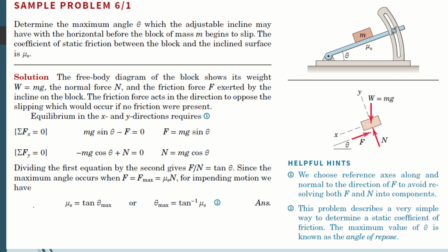So what is the maximum angle? Now this is again what you will get: the angle of friction, which we have studied in the second last article. How are you going to find this? As you know, a mass under the gravitational force field has weight mg. Since this weight acts vertically down toward the center of the earth, there is going to be a reaction force generated by this plank outward. This reaction force is going to be balanced by a component of the weight mg downwards and another component acting this way. So this is going to be your angle theta.